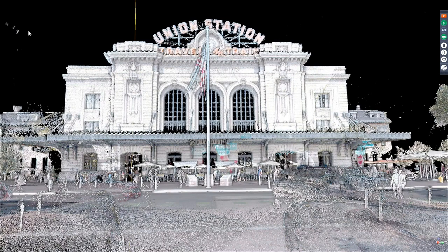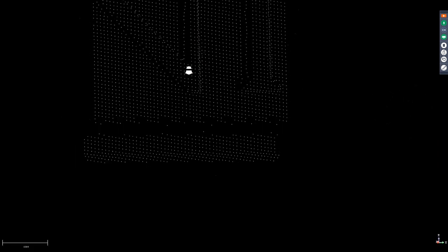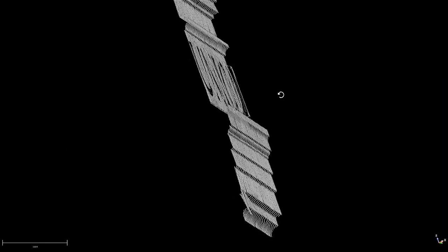Now, if I look at a single scan, this was actually at a pretty good distance. This was using the TX8. You can see a lot more definition, a lot cleaner point cloud. Now this was from a single station. Using stationary scanners, you would in fact be moving around, so you would see this position scanned from multiple positions most likely.